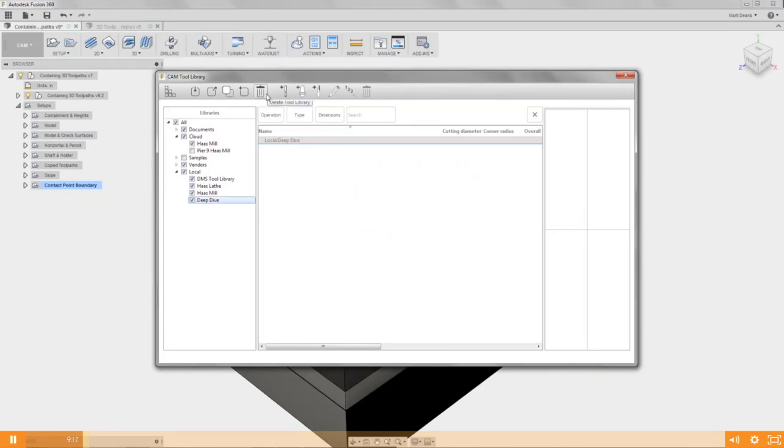And then I can, of course, delete a library. So once I have a library, especially if it's an empty one, I need to start filling it with tools and holders. To do that, over here we have our tool commands. The first 3 are all creating a new one: new mill tool, new mill holder, new turning tool. And then we have some editing commands, like edit a tool, renumber the tools, or delete the tool.